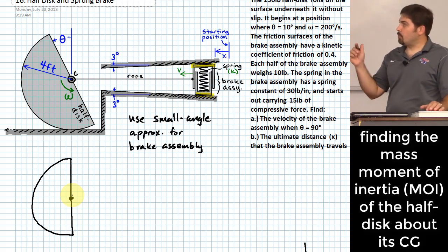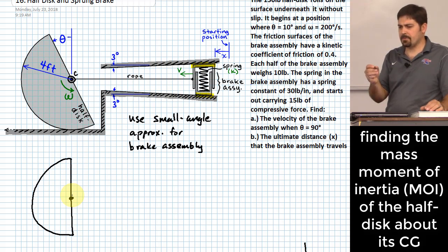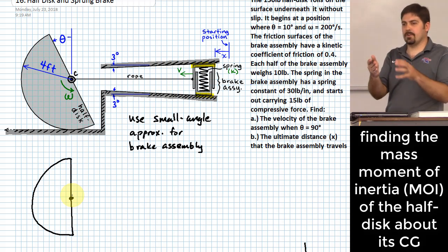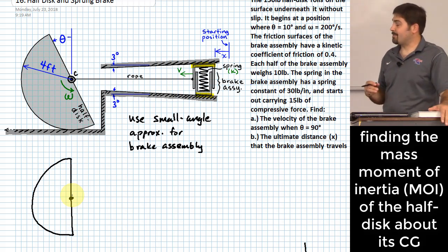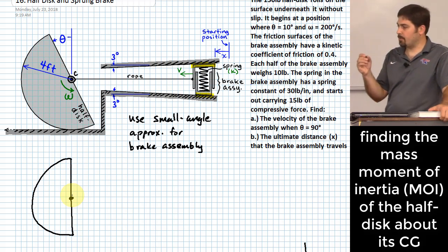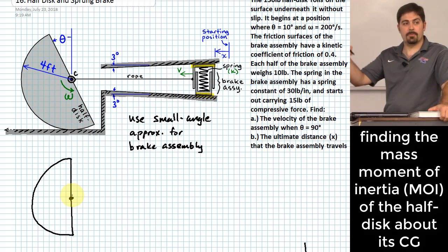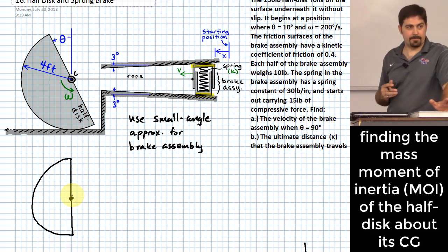Earlier in the course, we looked at a situation where I found a moment of inertia for a body, instead of around the center, around some other location, right? That was using a principle that you can take an instantaneous center. If you find the moment of inertia around that point, then you can treat it as if it's a purely rotating body, in which case you just have 1/2 of the moment of inertia around that axis times omega squared. This problem makes that, while maybe not impossible, impractical to do this way.